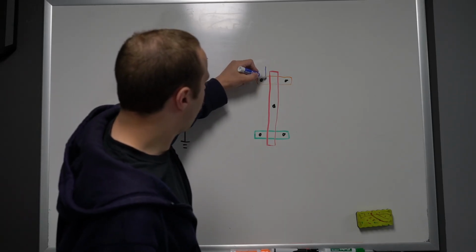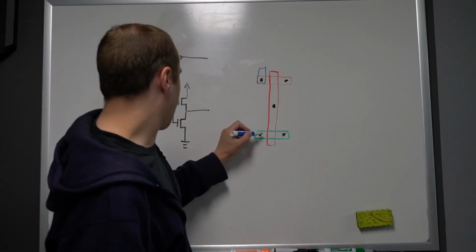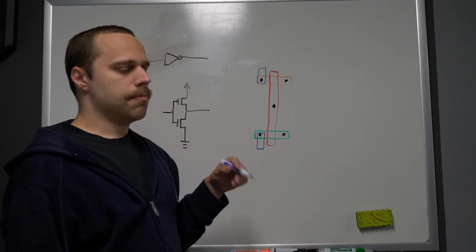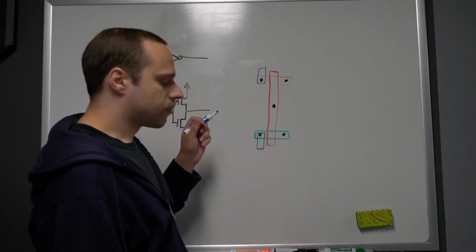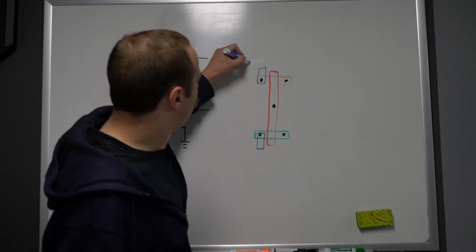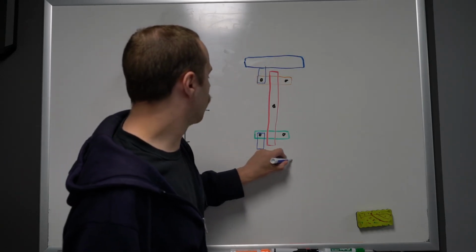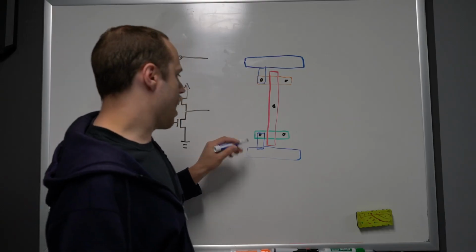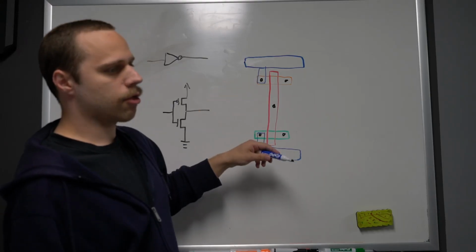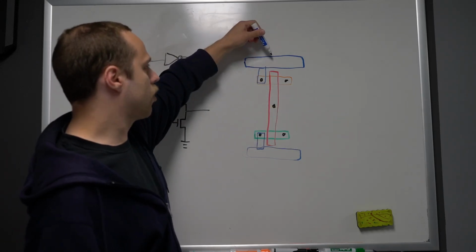And that now brings us to the metal layer. So we're going to add a metal connection on the power side and a metal connection on the ground side. And typically in modern digital logic devices, the gates are laid out in parallel rows of circuitry with rails of power on the top and ground on the bottom. And these then butt up against each other, so we have continuous metal tracks of power and ground, and then the cells are vertically mirrored from row to row. So the next cell above here is going to have the PFETs at the bottom and the NFETs at the top.